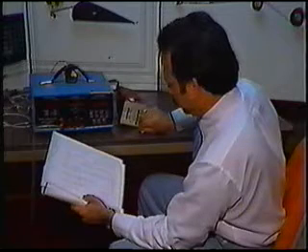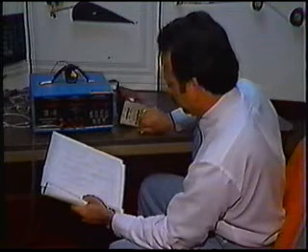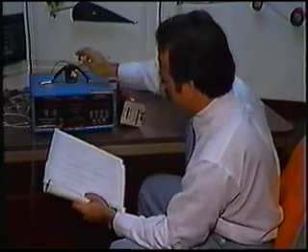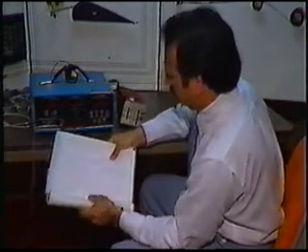We're adjusting the computer to achieve 2 primary purposes. Number 1, the computer must provide the proper voltage output to accurately drive the SAS indicator. Almost every adjustment made to the computer requires that we check the position of the SAS indicator needle. The second purpose in adjusting the computer is to provide the proper milliamp output to energize the SAS servo clutch. It should also be noted that some of the adjustments interact and affect other adjustments as well. The SAS indicator may also need slight tapping to ensure that the needle position is accurate.